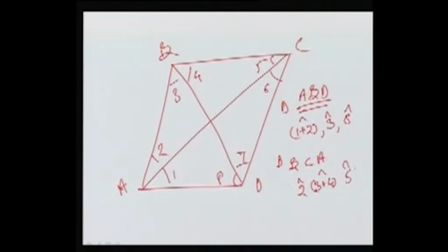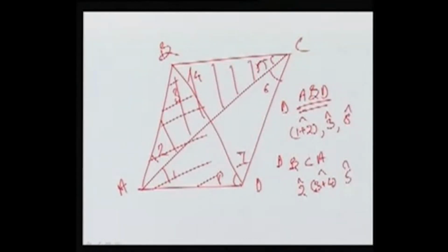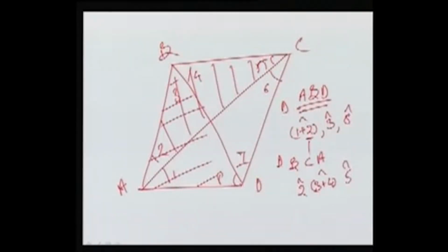So what we are seeing here is that if I adjust this base quadrilateral in parts, adjusting only this triangle first, I have the adjusted values of the observations inside. Then I can also adjust this particular triangle. Now the angle, for example angle number 2, has one value here and one value here. So angle number 2 is being adjusted in 2 different ways. So it will have 2 different values, which is not possible.